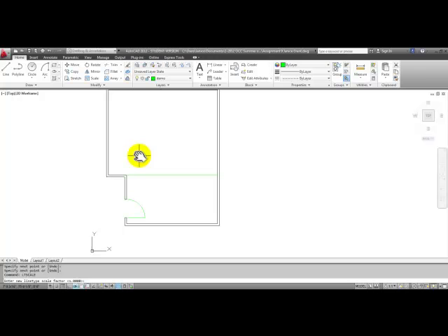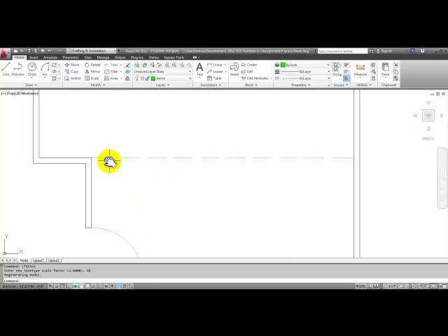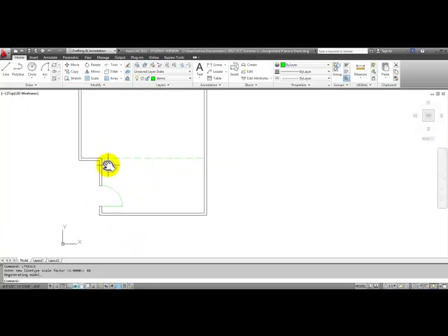and enter. And then for the new LT scale, you can refer to the scale factor sheet that I've posted online. This drawing will be plotted at 1/4 inch equals a foot, which establishes a scale factor of 48. So I'll type in 48 and enter, and notice that now I can see my dashed line. So I've increased the scale of that hidden line 48 times the size, or at least to something that's visible. The larger the drawing, the larger the text, dimensions, hidden lines, and border.